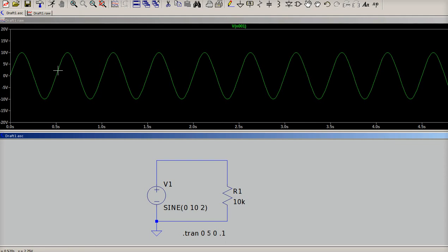So what you're trying to do is break this down into one, what we call, cycle. So if I start here and I do one cycle, I end back up at 0. And then I can do another cycle, end back up at 0. Another cycle, and I can keep going. So the period of a waveform is the time, being your horizontal axis on an oscilloscope in most cases, that it takes to do one complete cycle. Boom.